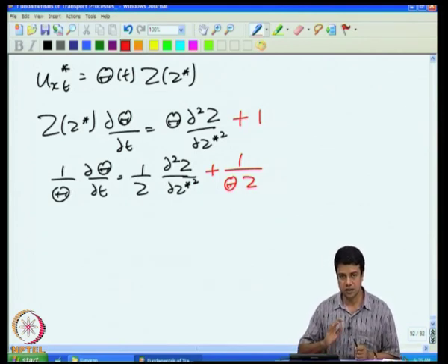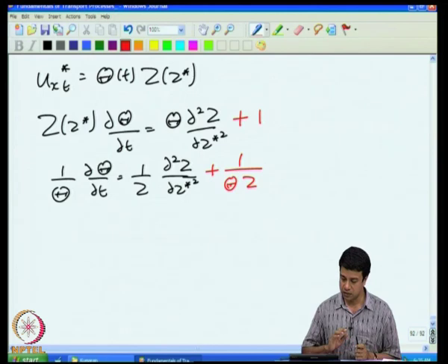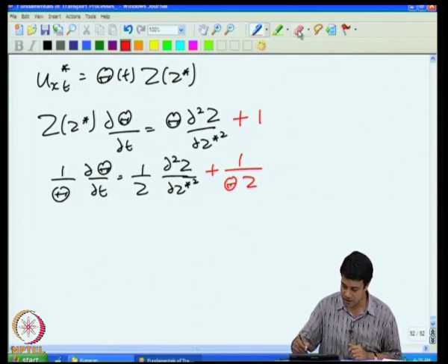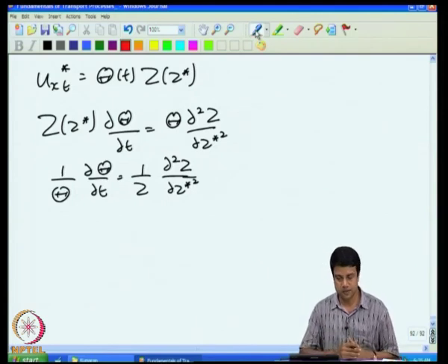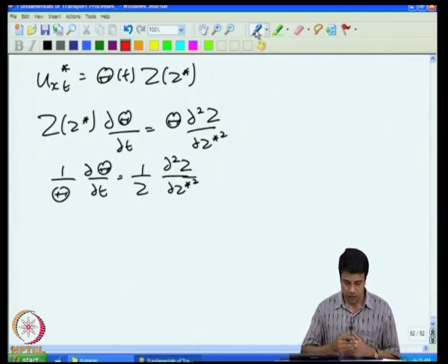It should not contain any inhomogeneous terms, and you reduce it to a homogeneous equation by subtracting out the steady part which already has the inhomogeneous term in it. Because we do not have these terms, we are able to do a separation of variables solution. So, it is essential. If you recall, when we did the flow between two flat plates, we had inhomogeneous boundary conditions.